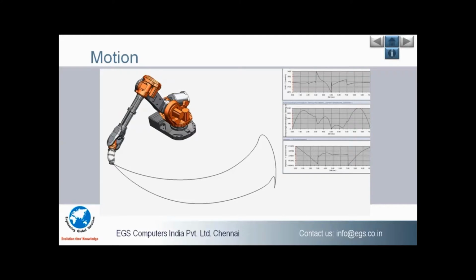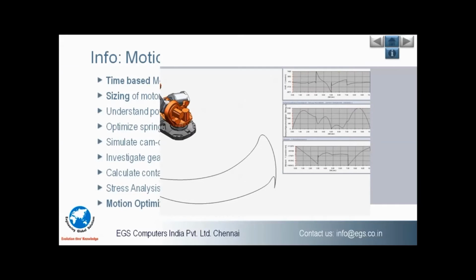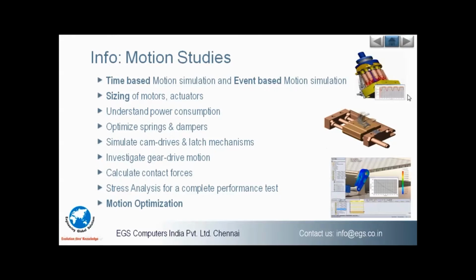Studying the behavior is the utmost priority for any kind of machinery industry. Using the kinematics, we can study the moving behavior of the components. For those of you who are using SolidWorks, we'll be working with large assemblies using the mates. All your advanced mates and mechanical mates will directly be linked to the motion studies using the links and the joints. So you can directly calculate all your forces from the joints.